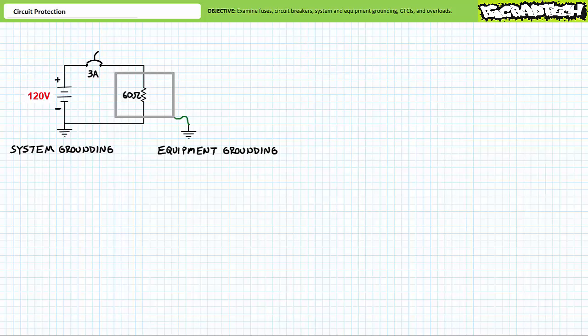With the system and equipment grounded in this fashion, if an uninsulated energized wire does happen to make contact with the conductive frame, there now exists an extremely low resistance path to ground. High voltage, low resistance. The circuit breaker immediately opens because current quickly exceeds the rated value. The accidentally energized frame is immediately de-energized, saving the operator and system from damage.